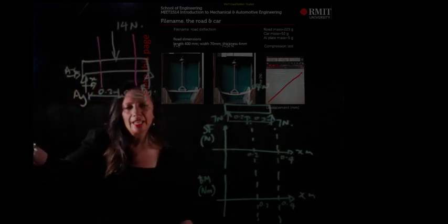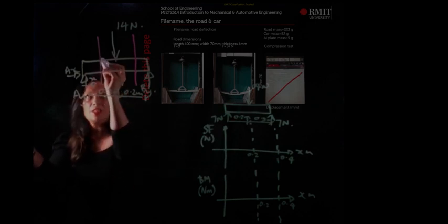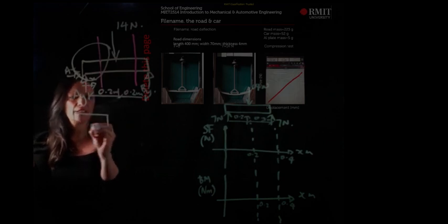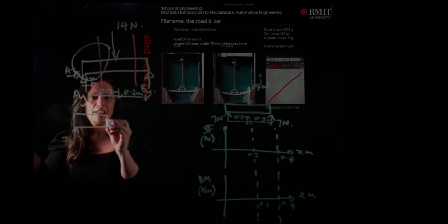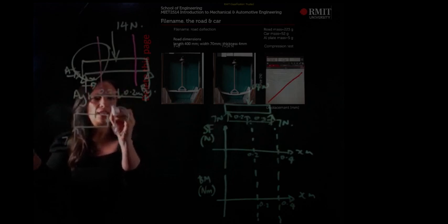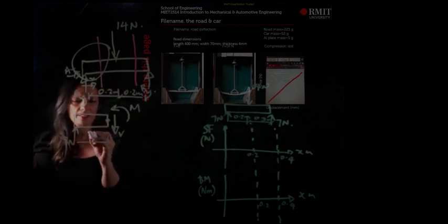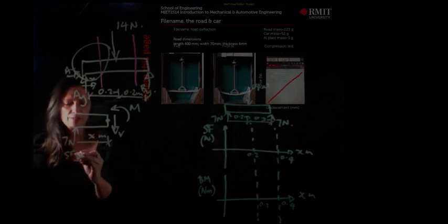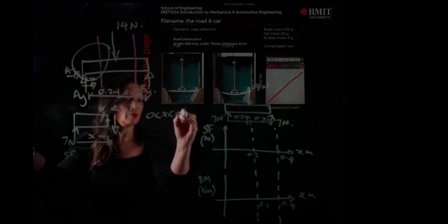So I want to calculate the maximum bending moment in this beam. The first section I'm going to look at is the first cut. Here we have 7 newtons, and we've cut the beam, so we have a shear force and a moment. I've said that this is x metres. If I want to find the shear force, our boundary is 0 to x to 0.2 metres.